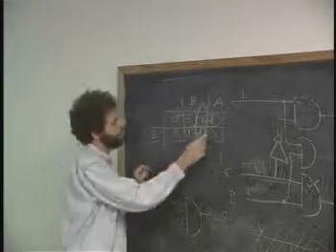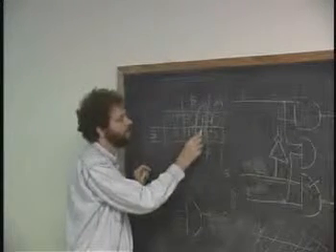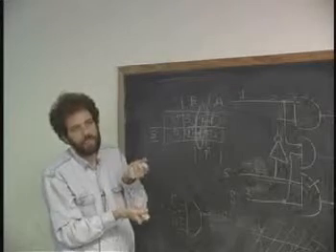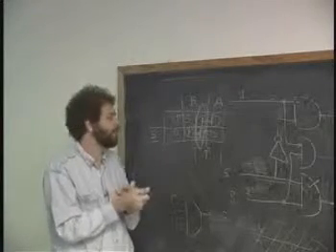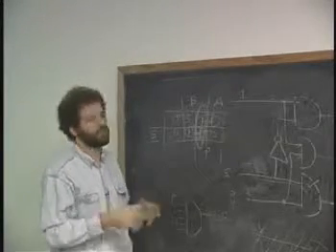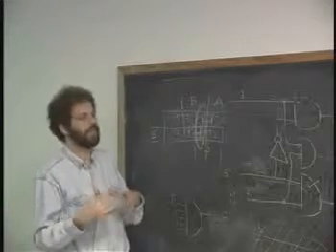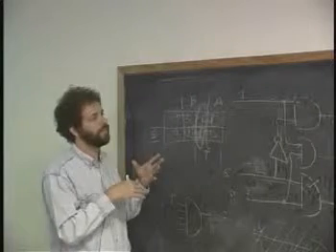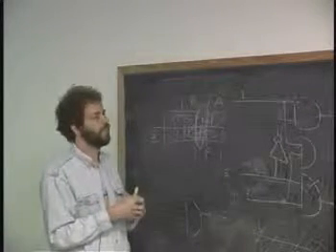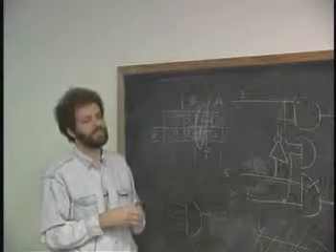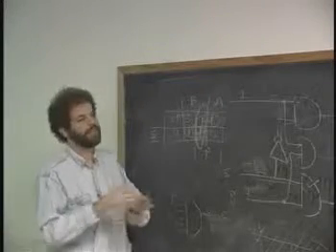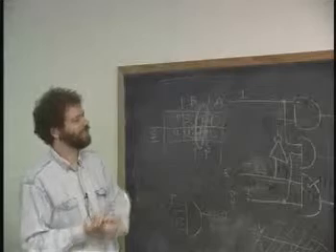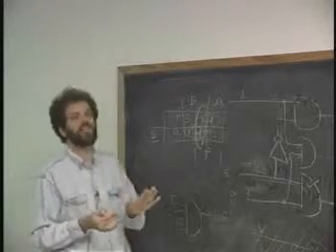For instance, when you go from here to here, there are 2 AND terms that turn on, and exactly what happens in the dynamics of the turn on. I could argue and probably convince you that that can't happen either, but I don't want to, because it turns out 0 to 1 and 1 to 0 hazards are actually an ill-defined thing anyway. It's the subject of a paper that I have half written, so I'm not going to bother to talk about it. They don't really matter.